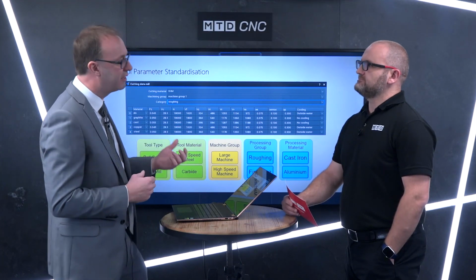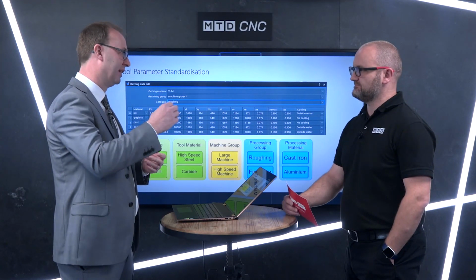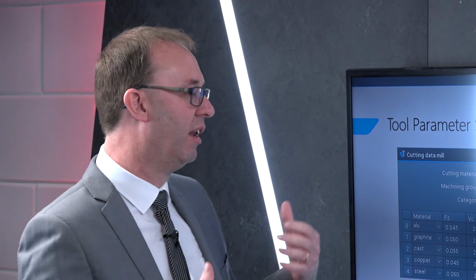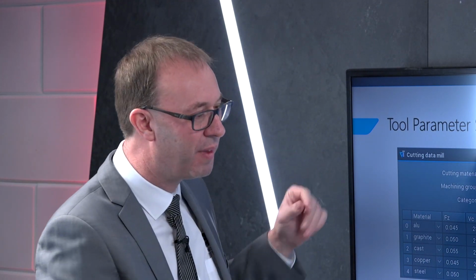So if we use the feature technology, we have conditional statements, where we can say, if this is the size hole we want to machine, the system will pick the correct size tool for that hole. It will even look at prompting: in the library, which tool library do I want to use first? Which is the sequence that I have to look for the tools?